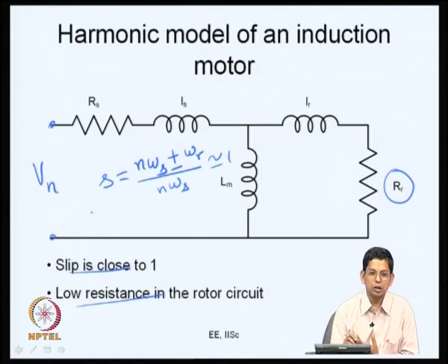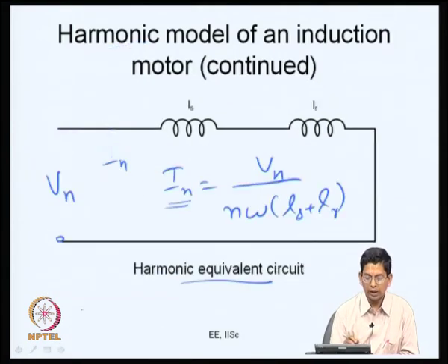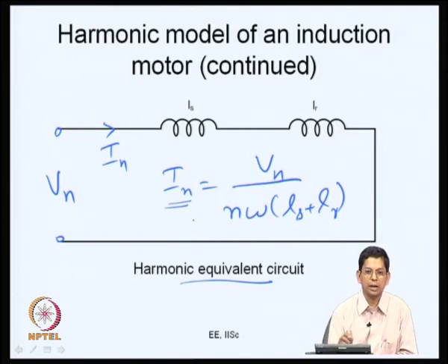So, the harmonic currents also produce the stator copper losses given by I squared R, and in fact, the resistance corresponding to harmonics could be a little higher because of high frequency effects such as the skin effect. So, the resistance could really be higher too, but we ignore those, and we want to consider the same resistance and calculate a value of IN, and this is an approximation that is reasonably valid for calculating IN now.